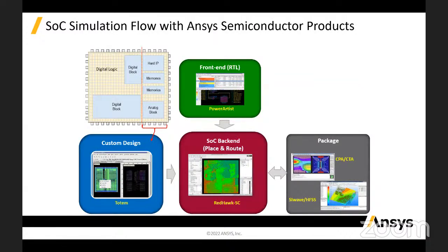Now let's look at the SoC simulation workflows with Ansys semiconductor products. During the front end of the IC design cycle, the designer creates the RTL description of the design. RTL stands for Register Transfer Logic. During this stage, the IC designers use Ansys PowerArtist to understand the power consumption of the IC design. Using the results from that simulation, the IC designer will look at improving the design from a power consumption and power efficiency point of view. I will expand on this in my later slides.